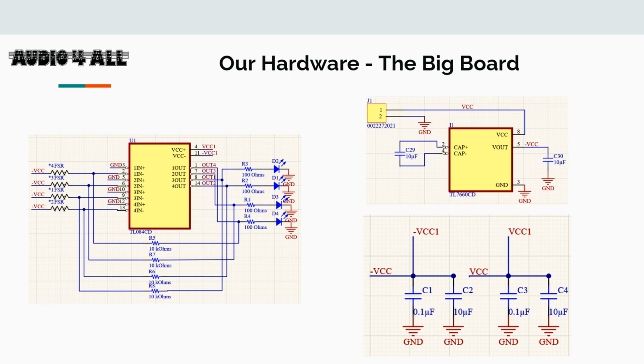There are 3 main components to our big board. High slew rate quad op amps were used to support 4 FSRs per op amp. The feedback resistor and FSR trace and space directly affect the conductance versus force curve of the sensors. A voltage inverting IC is used to provide the negative voltage required for a chosen op amp topology, which utilizes dual channel power supplies. Each op amp power input contains bypass capacitors for noise removal.